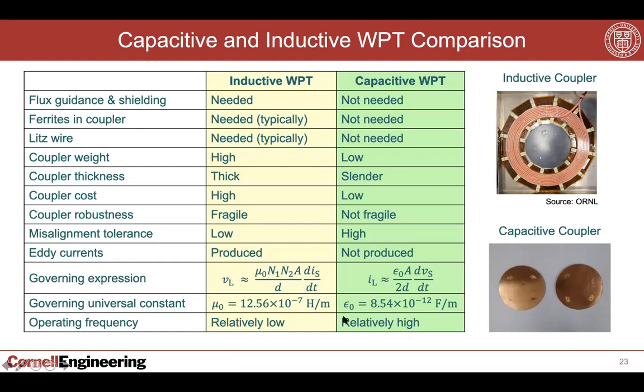in order to have a commensurate level of power, which is essentially what makes capacitive wireless power transfer so much harder, because of developing power electronics to operate at such high frequencies. For the kind of systems that I'll be talking about next, which is automotive or electric vehicle wireless charging, you have to go to high megahertz frequencies, whereby high means at least 6.78 megahertz, but even higher is better.